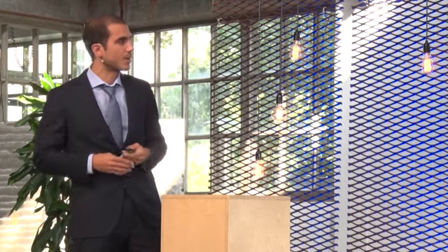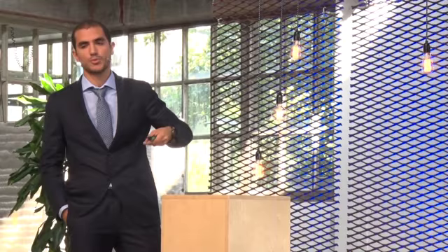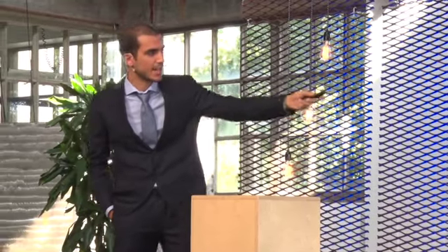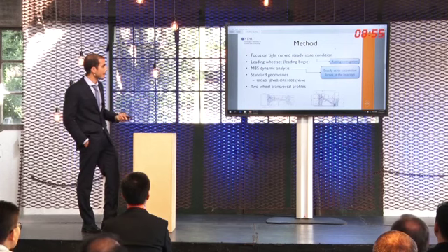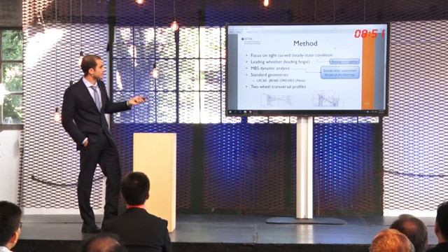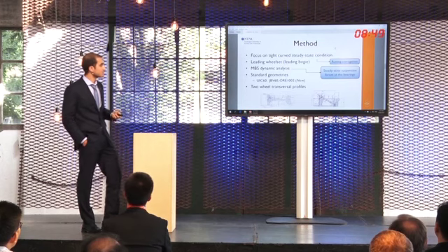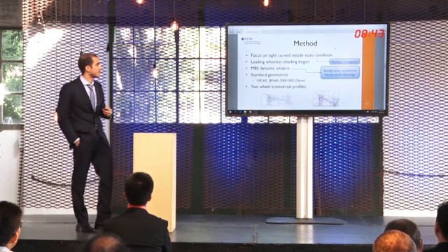The geometries are standard. And we have considered two wheel transversal profiles. On the left, an S1002 European profile, very commonly used in Europe, while on the right, a commonly used transversal profile in China, in the metro lines, actually. All right, this is going to be one of our parameters in the analysis.